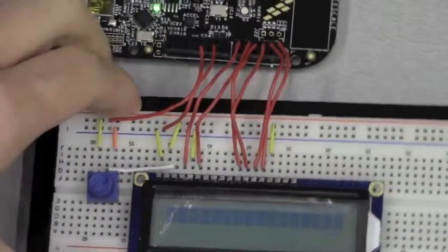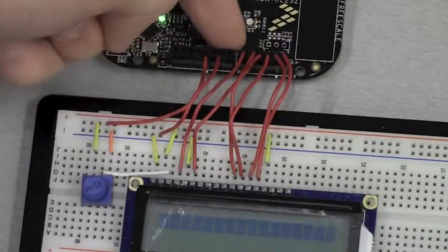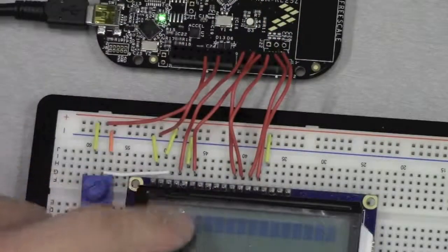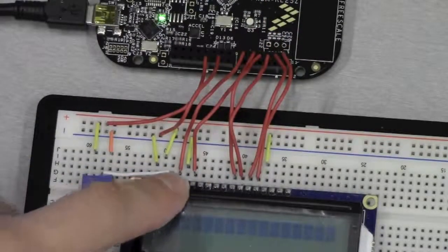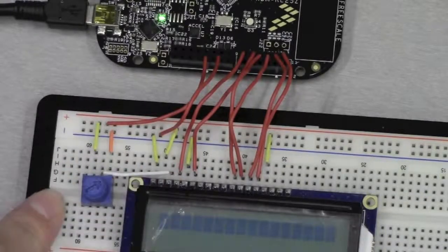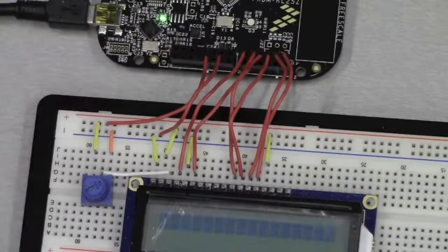And we're going to have to figure out what these pins are, because these are the ones that we use to drive the LCD display. So we're going to go ahead and do that in programming and just look through one of the little spec sheets on the KL25Z, or the image of it, and just map those pins onto our program.